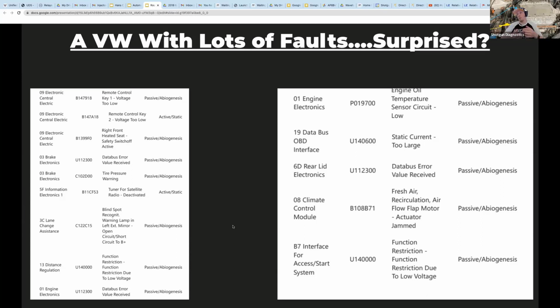TopDon does make several. They make a 30 amp one, which I think is very good for ADAS calibrations, wheel alignments, basic key on engine off testing. That one does 30 amps, and that's the TopDon Tornado T30000. And that one's nice because the cable's real low profile, so you can snake it under the hood and shut the hood all the way without crushing the cable. So that's real good for those. But if you're doing hardcore diagnostics or you're doing programming, you usually need more than 30 amps, or a lot of the newer vehicles will. So they make a T90000, which puts out up to 90 amps, obviously.